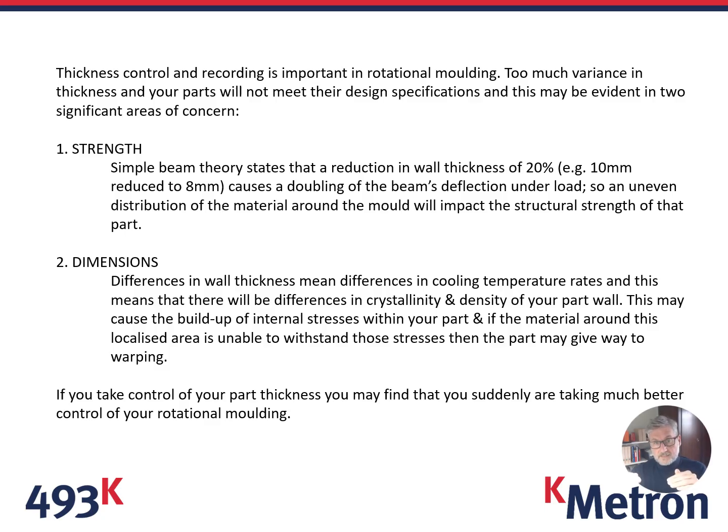Variation in wall thickness will also have an impact on the rate of cooling of the part and thus the crystallinity and, potentially, the level of warpage that you will experience. So in order to minimize these deflections, in order to minimize this warpage, it's important to ensure that you've got a well-distributed wall thickness of your part.